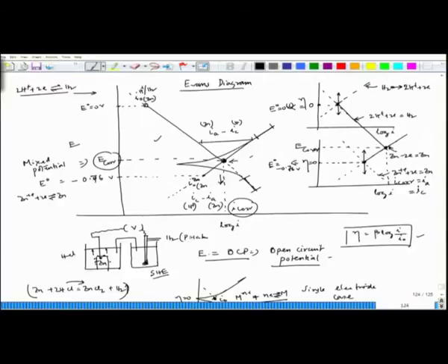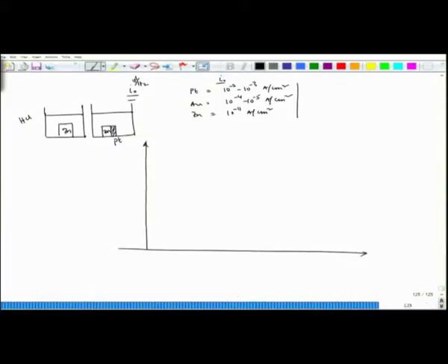These Evans diagrams are not the practical diagram, which is I applied versus potential or potential versus I applied. This is basically potential versus log I, as per the polarization or the Tafel equation. We will not consider here what happens if we go on the positive side or negative side and what would be the variation of I applied.